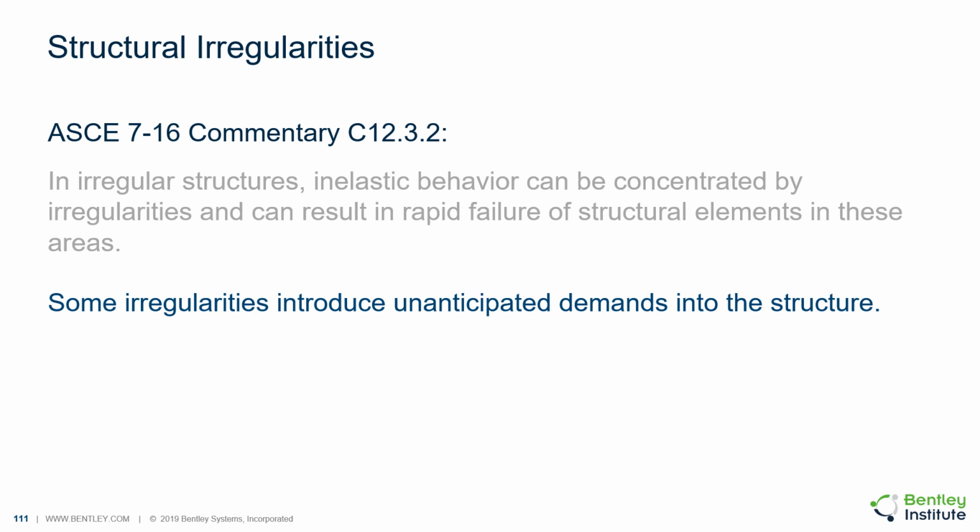An example of this would be torsional irregularities. When a structure is susceptible to twisting, that behavior may be amplified in an earthquake, resulting in shear forces due to the rotation adding significantly to the direct shear forces.